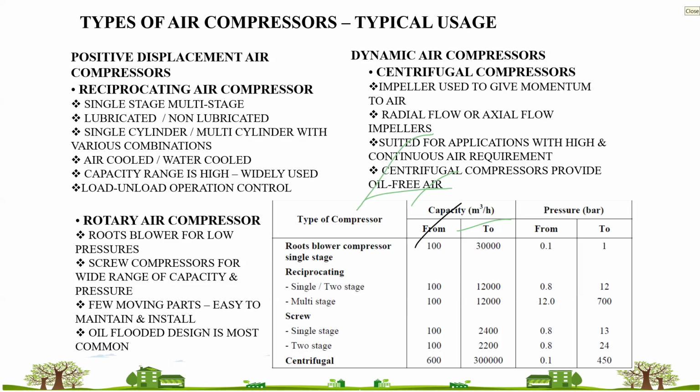Okay. So both the criteria are main selection criteria in the air compressor. In a multi-stage compressor, if you are using a two-stage compressor and producing air at 12 bar, you'll be setting those two stages as 1 to 6 and 6 to 12. So you'll be having 6 as the pressure ratio in both the stages. But if you are doing it in single stage, 1 to 12, it will be a higher pressure ratio.